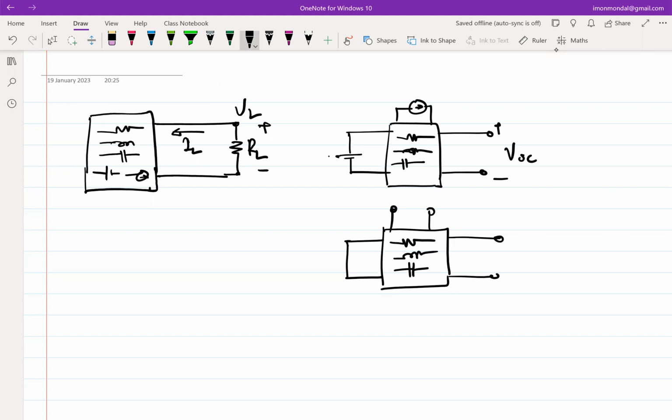So basically, by the way, this is exactly what we will do later on in the course. We will need to figure out the resistance, impedance, admittance of a network. Initially, we will be putting voltage sources, current sources, and figuring it out. Later on, I'll assume that you are comfortable enough to look at the circuit and figure out what it is. But essentially, the practice that we'll be doing is adding a test voltage source here. Let me call it a test voltage, V test. It need not be a DC, it can be an incremental source, it can be an AC source, depending on the situation. And we will be finding out the current that is flowing, I test. And V test over I test will be your impedance, right? So maybe one third of the course will go in finding impedances. So it's critical.